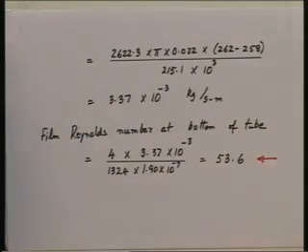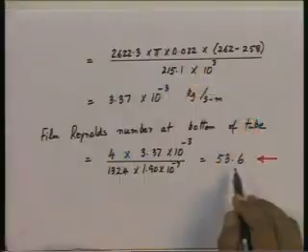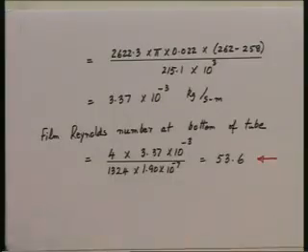Now, you might want to note that the Nusselt formula which we have given is generally experimentally found to be valid up to film Reynolds numbers of about 30. Above 30, ripples form on the condensate surface, because there is more condensation taking place. Film Reynolds number higher means more condensation rate. So, above 30 there are ripples on the surface, and these ripples tend to enhance the heat transfer coefficient a little. It is still a laminar flow, but they tend to enhance the heat transfer coefficient by 10, 15, 20%. This is what is observed experimentally.